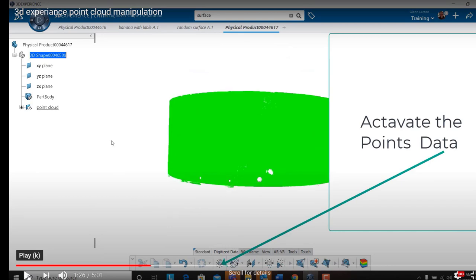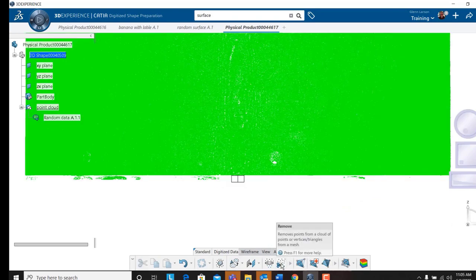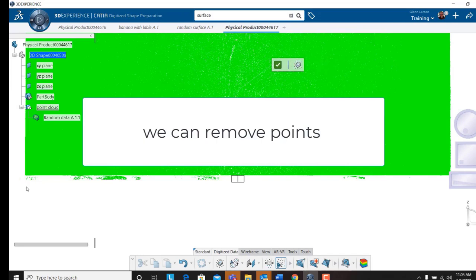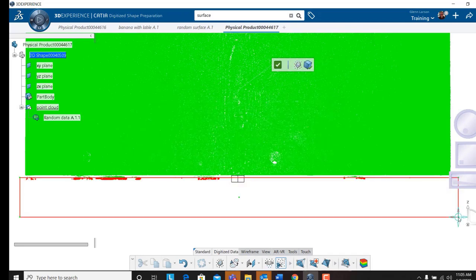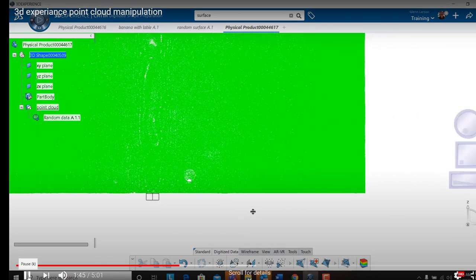And what we're going to do is just grab all the data and activate it so it's all active. We make sure we can touch it and use it and delete it and edit. So here I'm going to take some of the random points out that I know are going to, because when you start filtering, it's going to go statistically. So you want to filter as clean as you can.